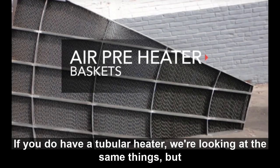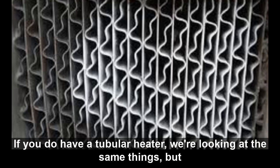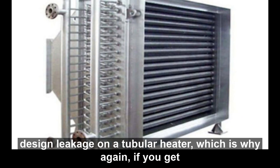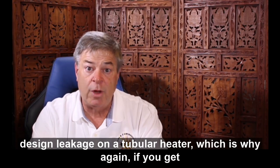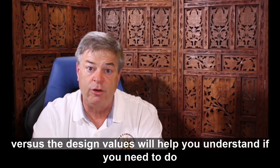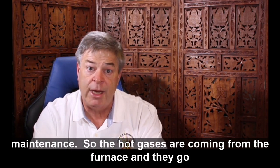If you do have a tubular air heater, we're looking at the same things, but your design leakage is probably a low number, probably less than 5% design leakage on a tubular air heater, which is why, again, if you get some leakage or holes in your air heater, looking at the actual leakage versus the design values will help you understand if you need to do maintenance.